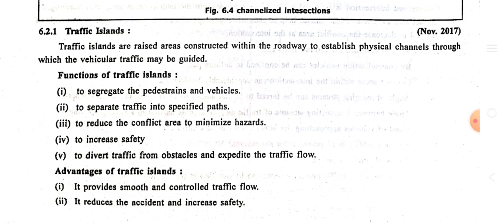So for that purpose you construct an island by stone or by blocks. So this type of construction, which is high enough from the road level to divert the traffic, is known as a traffic island. So here some of the functions of the traffic island are to separate the pedestrians